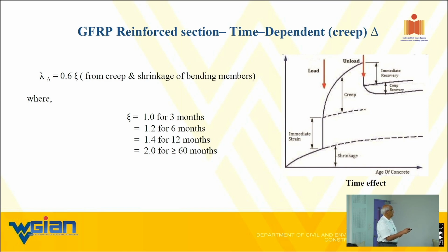This is the instantaneous deflection due to dead load or whatever, but after it hits the dead load, there is a gradual increase. In the increase process, whatever the live load effect you have, we are only considering 20% of that over and above the dead load creep.